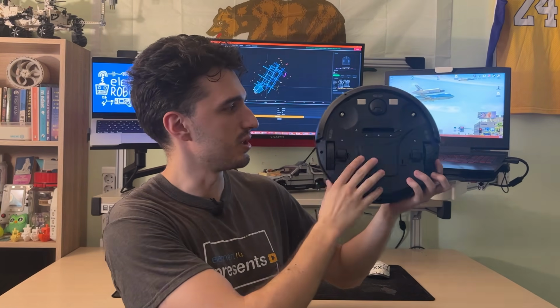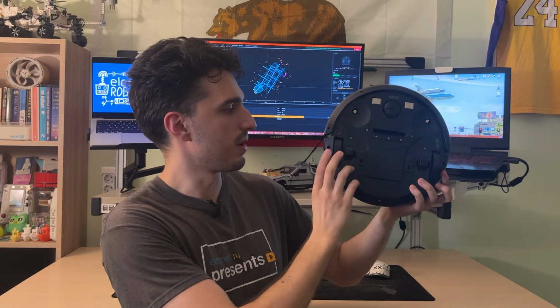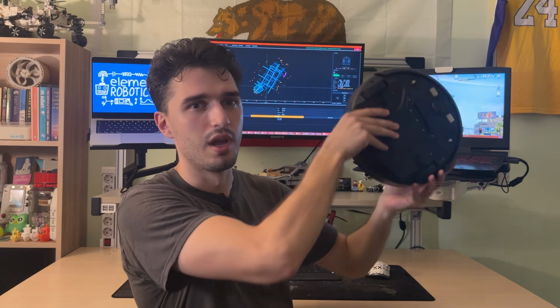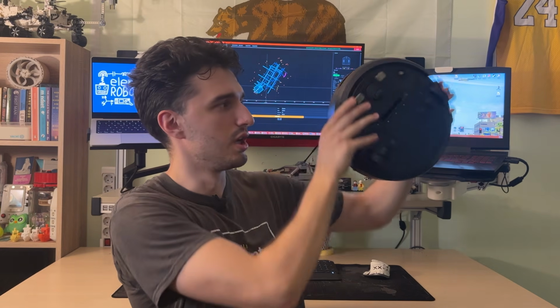Let's talk about the robot that we're gonna make, the differential drive robot. Where can you find them? Mostly on your floor, so something like this. The vacuum robot is the prime example of a differential drive robot. If we flip it around and see what's underneath, you can see that we have two drive wheels and one caster wheel. How it turns is, as I already explained, if you turn this wheel faster than this one, the robot will turn this way. You can also turn one in one direction, the other in the other direction, so you can move on the spot and so on, but we'll talk about more of that later.